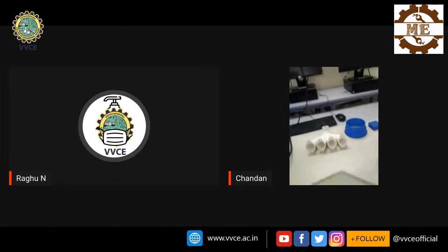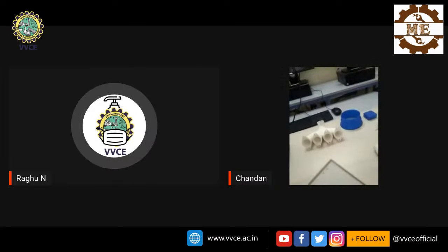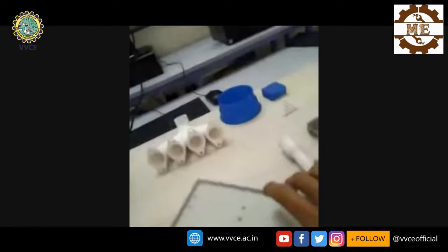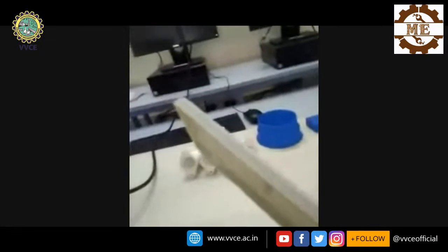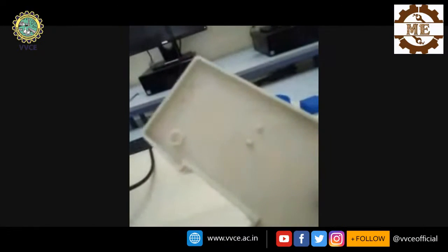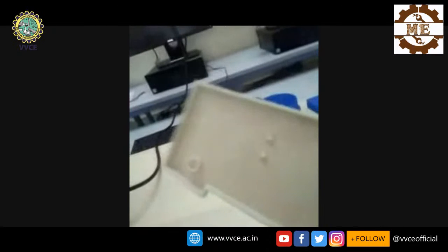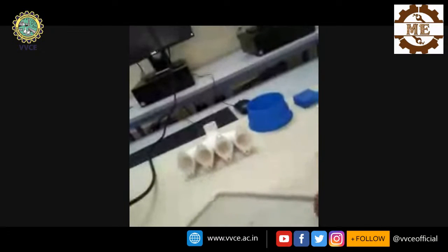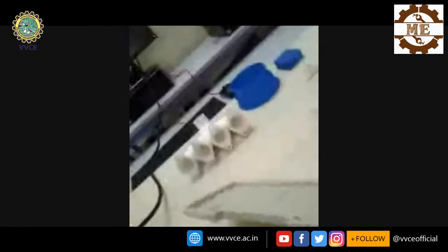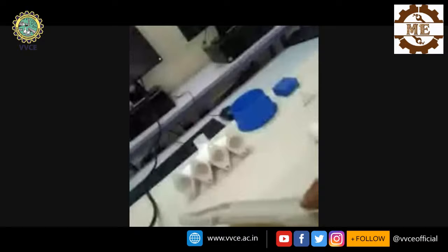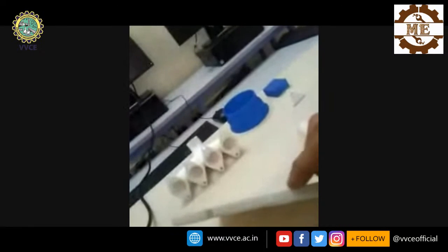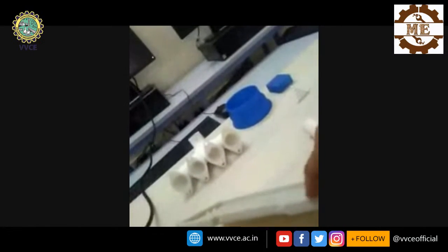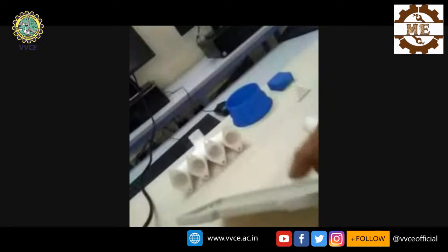Similarly, some boxes for some companies, or components where we faced a problem and it is not completely printed. It is basically half printed because the complete component cannot be shown, as it is proprietary to the company. These components were printed only halfway and then stopped, because there was a peeling effect. Once one layer had peeled out, the further component being printed above it was not sticking. That was one problem we faced. I don't know, maybe it was a temperature effect, or maybe the component became very large.